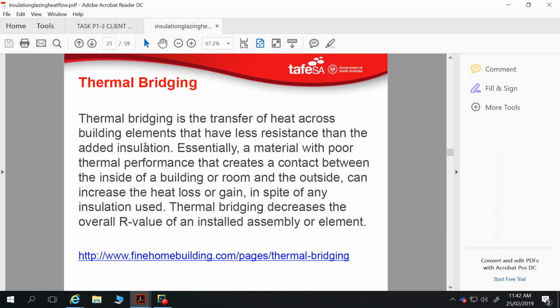So we talked about conductivity of materials before, and I spoke about steel frames requiring that air cell insulation. It's about thermal bridging. Thermal bridging is important for all of your building fabric, including windows. If you are spending a lot of time and consideration and money on producing a house which is thermally comfortable, and the cost of going to thermally broken window frames is not too much extra, then I can really see the sense in doing that.